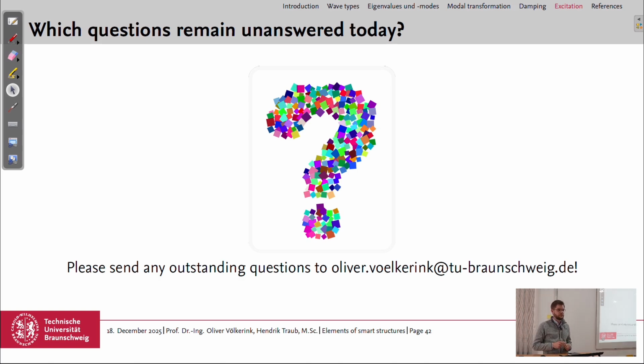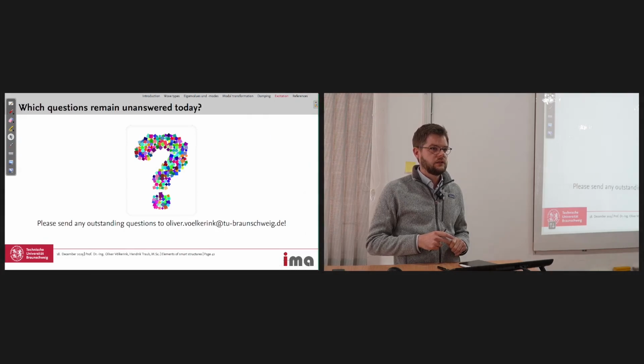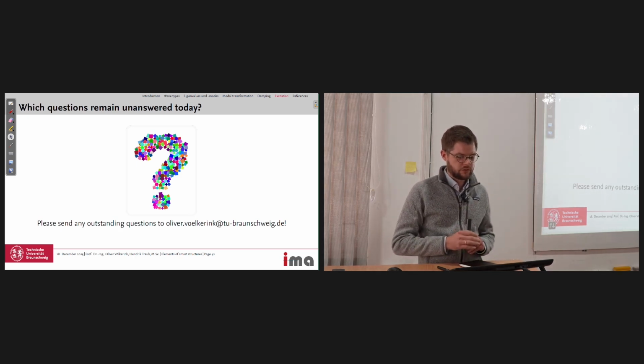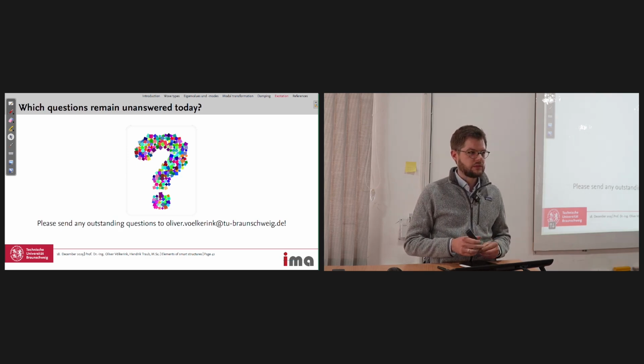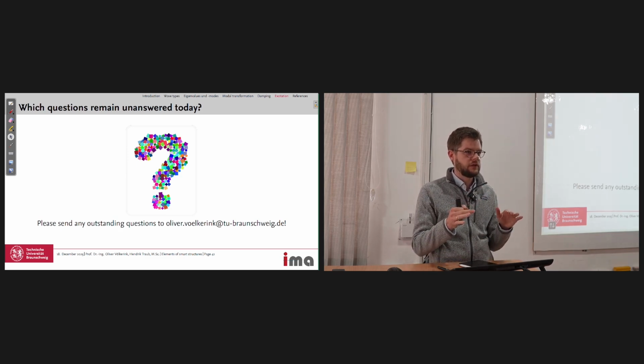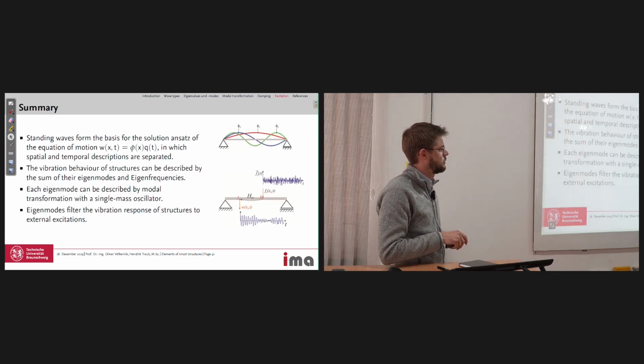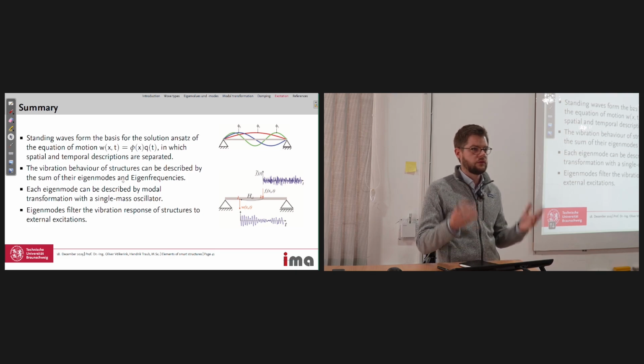Transverse you can consider as no force, but in this direction there is a net force. So can you model this as a free vibration? I'm not sure if I got the question right. So in aerospace structures, thin structures, we would also have these kind of bending waves and no longitudinal waves, I would say. And we can use this approach with the modal analysis also on the whole aircraft structure.